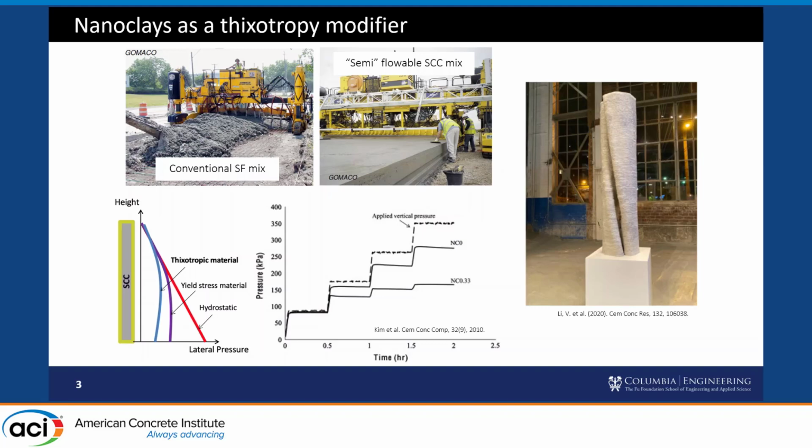Work by Wang developed a semi-flowable SCC that can consolidate under its own weight, eliminating the need for the external or internal vibration, but still exhibit that structural buildup for shape stability after extrusion.